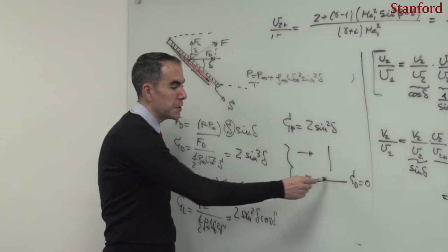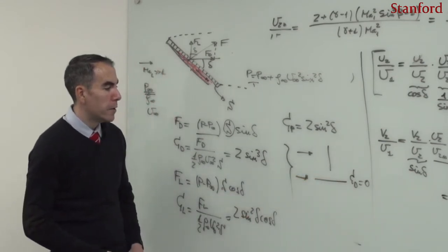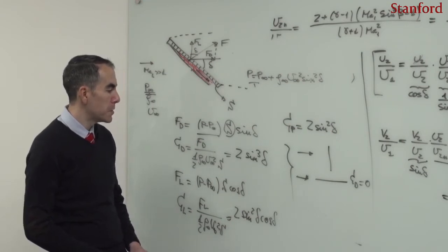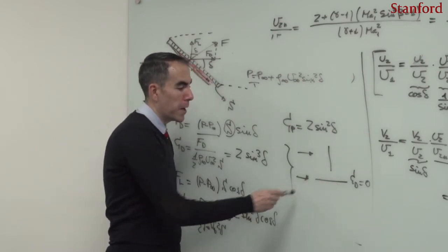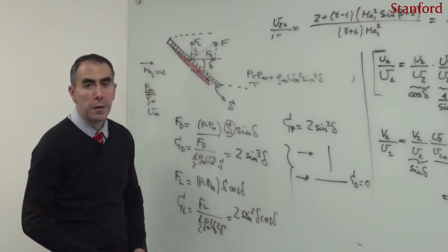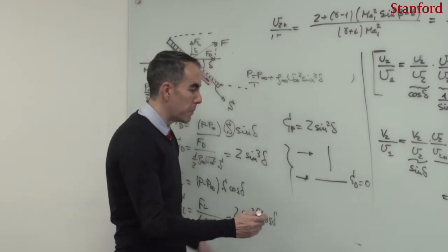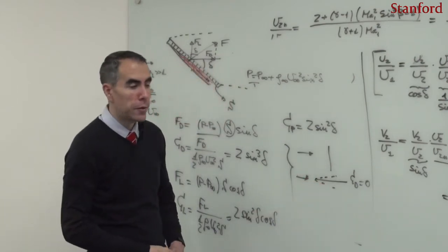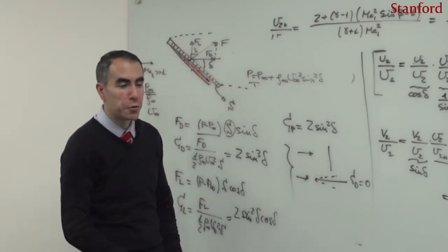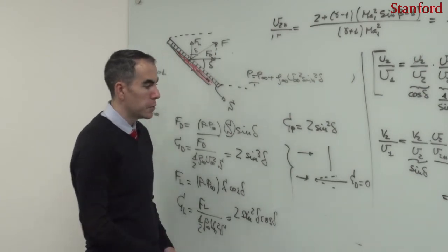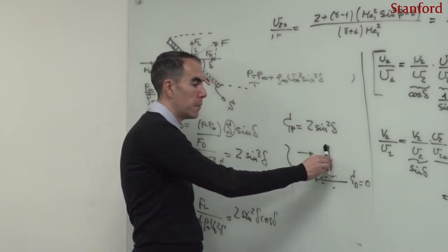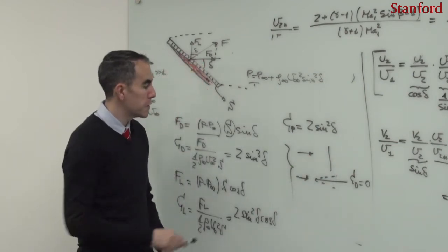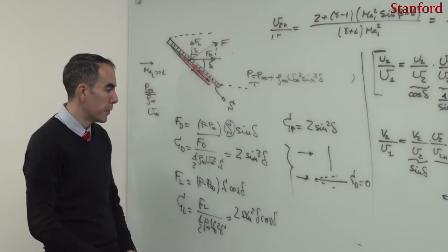Well, that the drag coefficient is 0 when the plate is parallel to the stream is not actually what happens in reality. What happens in reality is that when the plate is parallel to the stream, there is a boundary layer that develops around the plate, and then you have a drag force acting on the plate, which is of viscous origin. So as one turns the plate and makes it horizontal, some of this theory is going to break down.